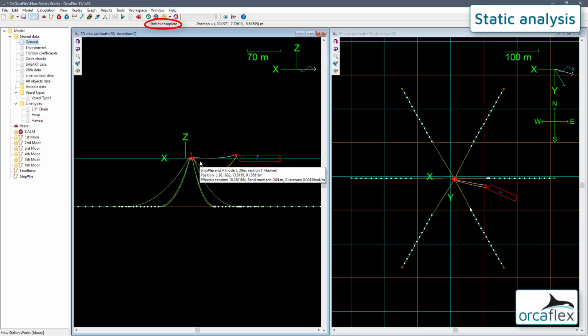We've learned that increasing the damping adds control, but at the expense of speed. To achieve an efficient calculation speed, it's best to find the smallest damping level that still results in convergence. But what will happen if the level of damping is too low for the system? As my model is quite stable, I'll need to cheat a little to demonstrate this by setting very low levels of damping that I would never recommend using. The purpose is to show you visually what happens when there isn't enough damping.